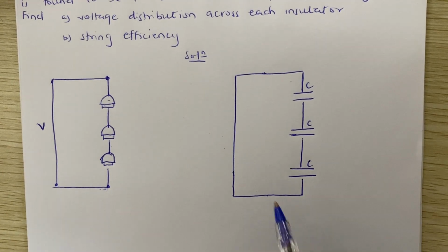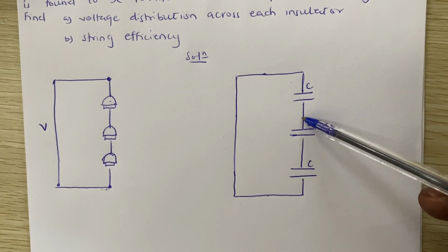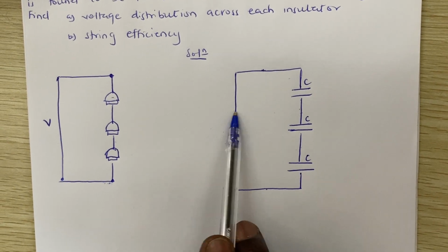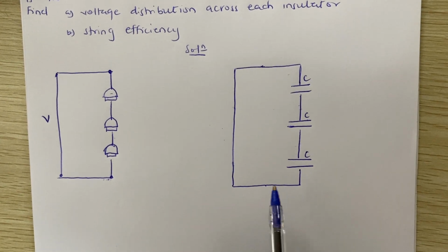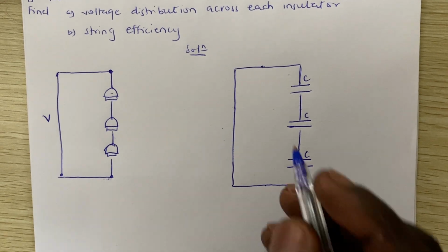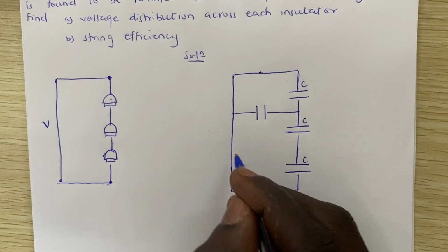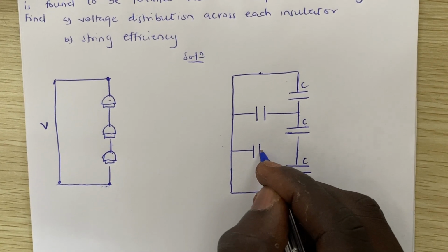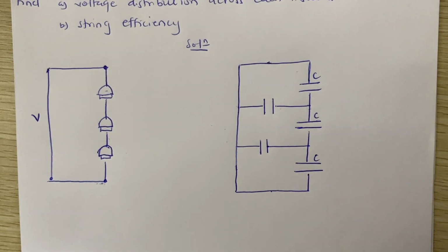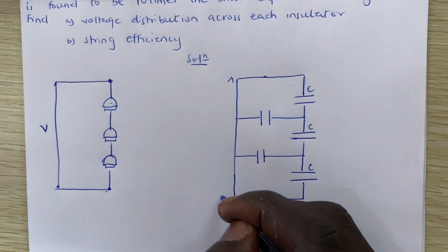But interestingly, this is a tower and this is a metal, and in between these capacitors two are metals, right? So it means that between these two metals there is air. It means this also acts like a capacitor. So we can also represent in between these metals with capacitors. I hope you understand that. Yeah. So we can present this with capacitors, this with capacitors, like this, right? Good.